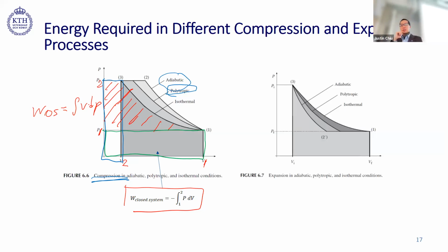And then also it's very important not to mix this with the storage period. We can say it's an adiabatic storage period where we don't have heat loss, because if you're having compressed air at 700 degrees, the system would very likely lose heat. And very often we also use the term adiabatic compressed air energy storage during this storage period, where we have good insulation, and that's slightly different from here. This is the adiabatic compression and not the adiabatic storage, right? But the conclusion from these graphs would be that isothermal would be the process we would prefer. Sure. Yes, it is.